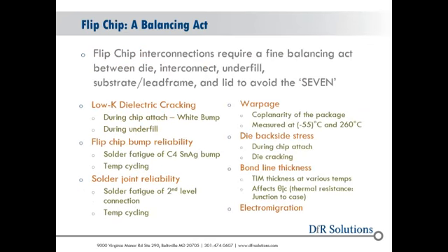So it's low K dielectric cracking, which I talked about, what some people call a white bump or bump cracking. It can occur during chip attach or during underfill cure. We're worried about flip chip reliability. Really, we're just talking about temperature cycling. The dimensions are typically too small to worry about any kind of mechanical shock or vibe for all practical purposes, even though we continue to do the testing. Don't really know why.